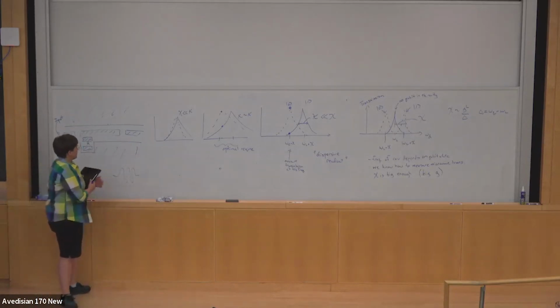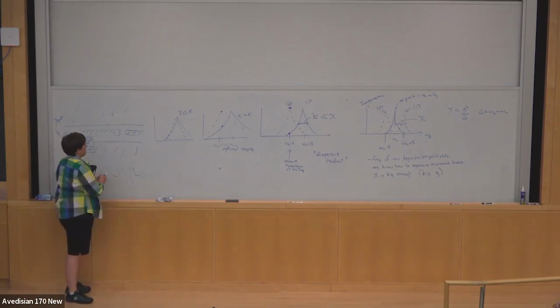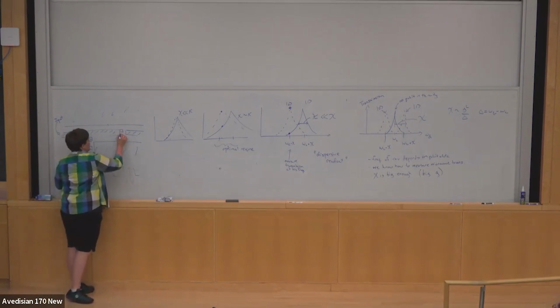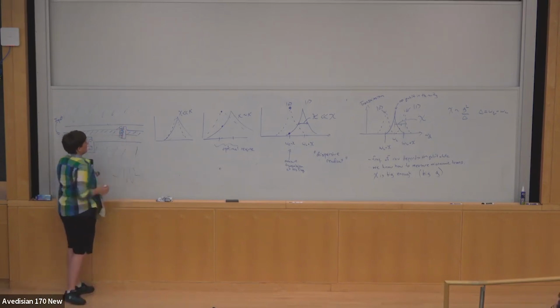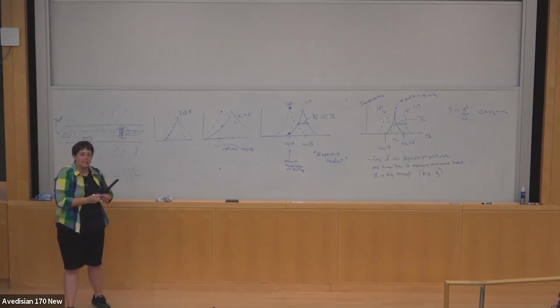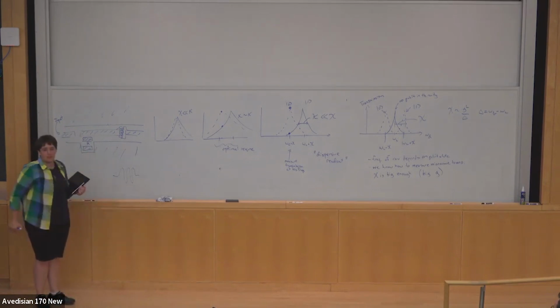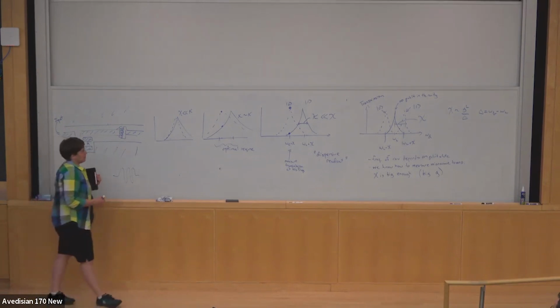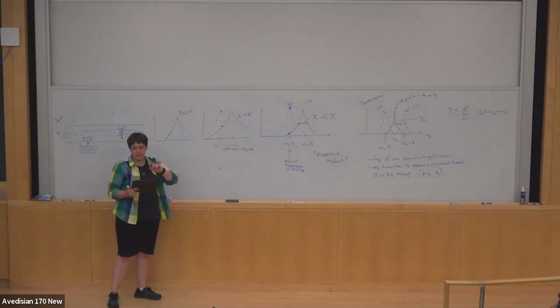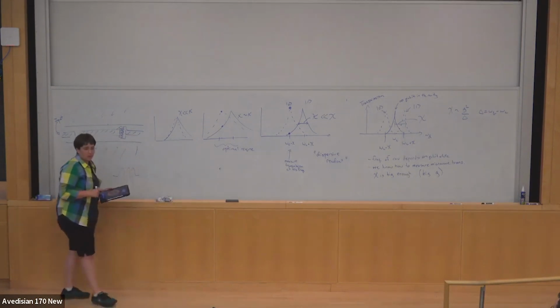You can change the size of these coupling capacitors. If you want more line width, you just turn this into a big interdigitated capacitor. It starts to look like two interlocking castles, and then you can get a lot more coupling. So it's actually very easy to control, and the native line widths are large enough that this is easy. And so it works really, really nicely.